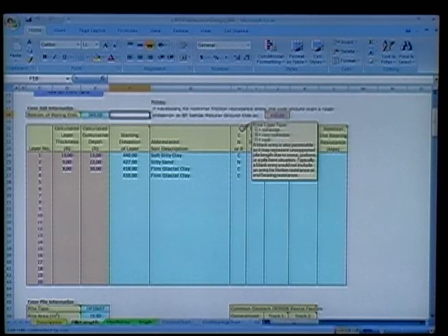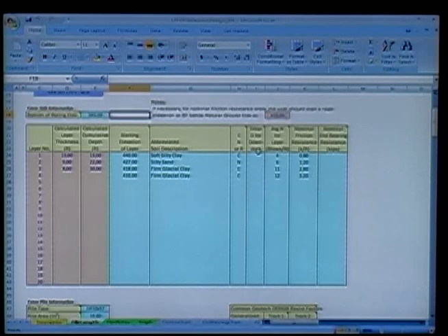R is for rock, if you got rock. If you're going down to rock. D is for down drag. So all the layers, the compressible layer, that gets a D, and all the layers above get a D, right? Because they're all going to settle and drag on your pile. That's talked about here as well.